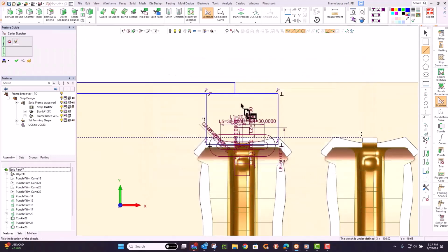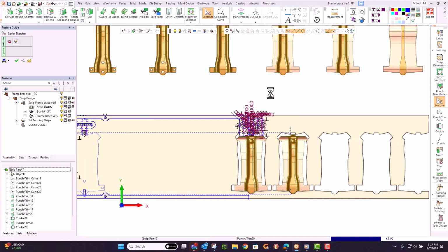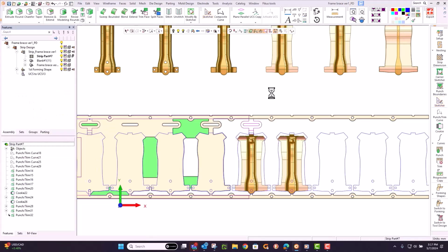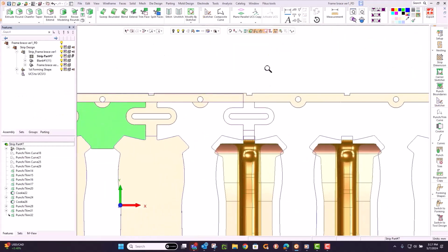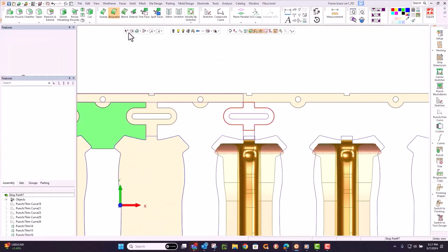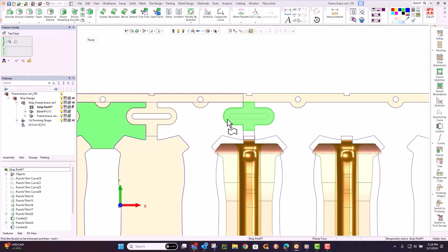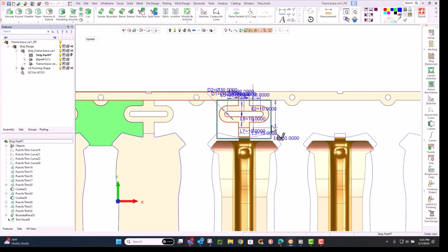And everything here is based upon parametrics. It's based upon the standard solid modeling principles. So it's a very simple, easy CAD system to work with. We'll put a quick little face in here where we know that expanded web needs to go. And that being said, we can simply adjust it. So I know it's going to expand out to meet the part. We know that distance, we make an adjustment in the sketch, and then we'll see as that expanded carrier transforms into an opened up, expanded web.